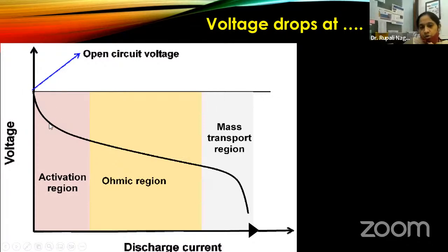Then again, whenever you are overcharging for a long duration of time, and if that is your habit, you're actually playing with the life of your battery. So it's good if you operate it not at the extremes, but in this region. Here the changes are reversible, they are linear, and hence it will help in enhancing the battery life.